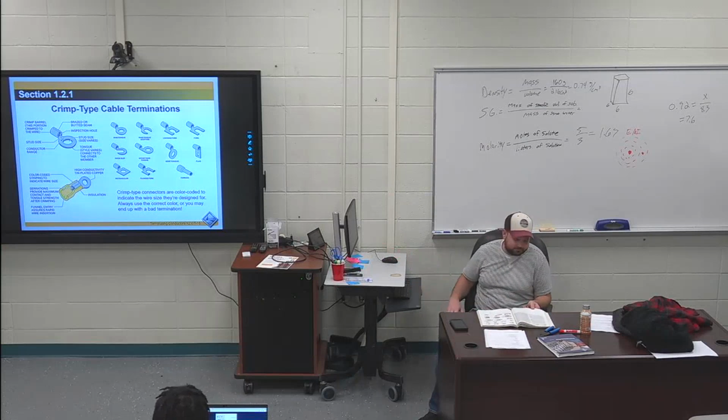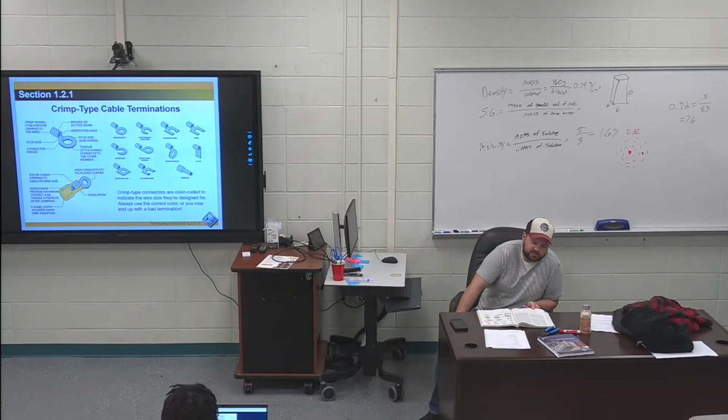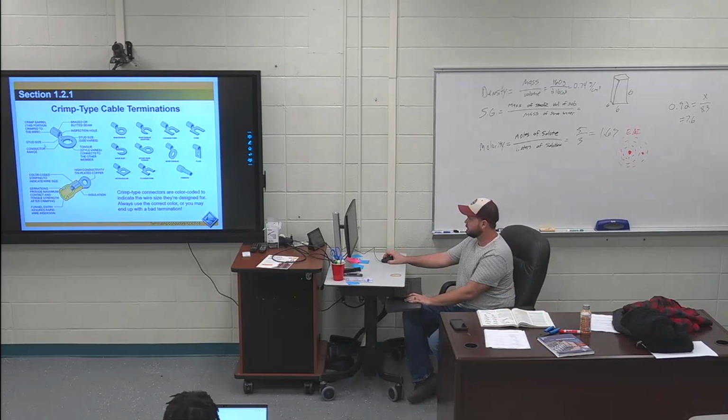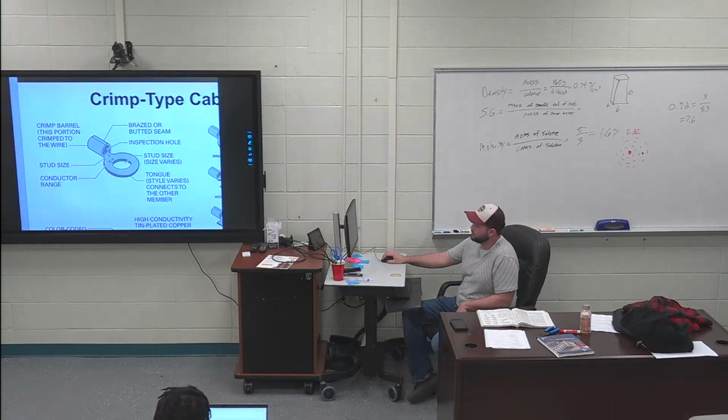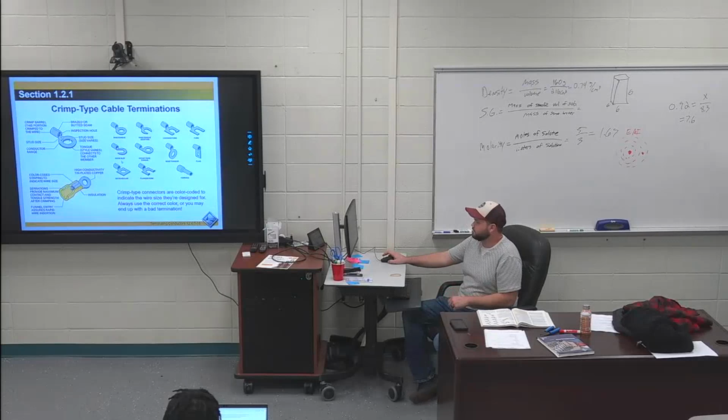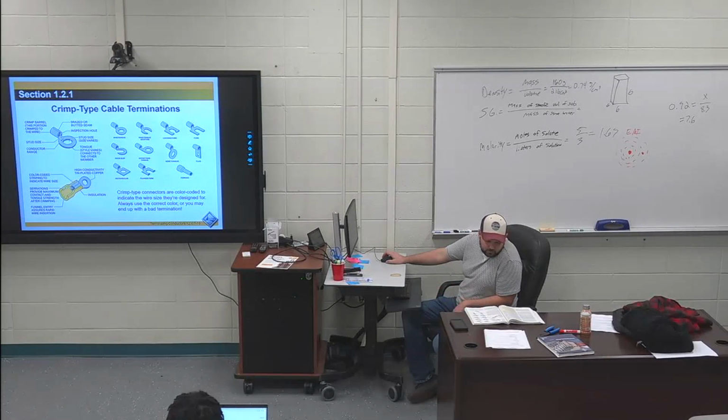Okay, you flip over to page 8. 22 to 16 gauge is red, 16 to 14 gauge is blue, and 12 to 10 gauge is yellow. It's not a bad thing to know. But another useful part of this is a lot of times the wire size is stamped right there on the tongue of these. So you never try to put like a 12 gauge wire. Like I've seen people trim some of the strands of wire off so they can fit it inside of these barrel connectors. Don't do that. Get the right size barrel connector or crimp connector for the size wire that you have.